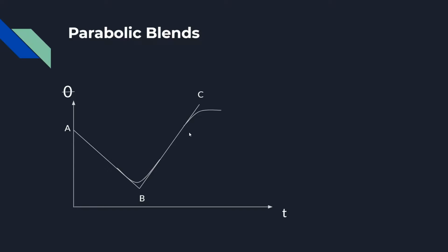And with a little bit of math, you could calculate what the ideal velocities should be and how much the time it should be from here to here, and before it starts a parabolic blend, how much of time it would take to undergo the parabolic blend, and this would be symmetrical, etc., etc. And then again, what should be the ideal time to start off the parabolic blend to have these changes.